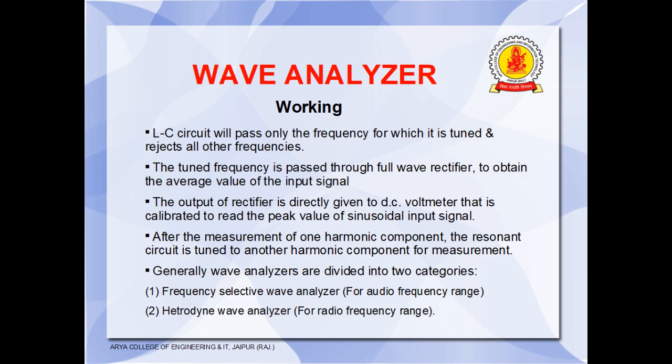Actually, wave analyzers are divided into two categories according to their frequency range. The first one is the frequency selective wave analyzer, which works in the audio frequency range, and the second one is the heterodyne wave analyzer, which is used for the radio frequency range.